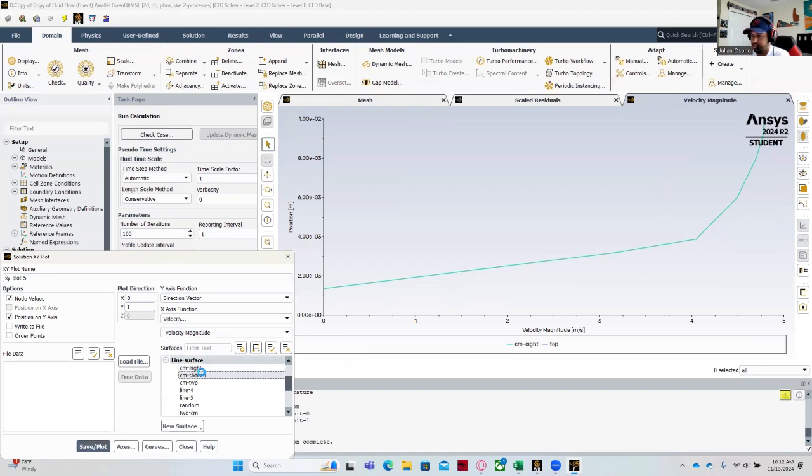And then lastly, at 16 centimeters from the edge of the flat plate, it'll look similar. It's just as you get further from the top surface of the flat plate, the velocity will increase, getting closer to the velocity at the test section until it hits the boundary layer where it's 0.99 of the velocity of the test section. That's part B. So next we plot the wall shear stress along the flat plate.